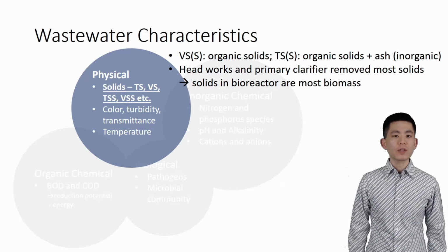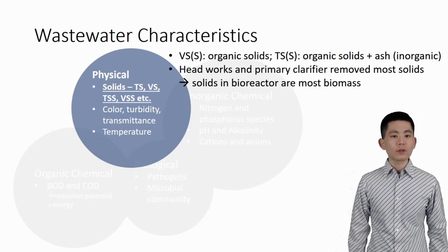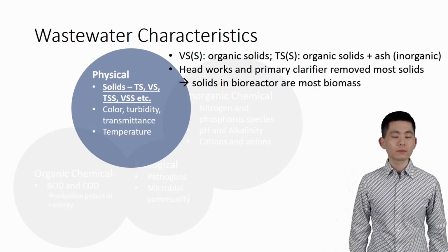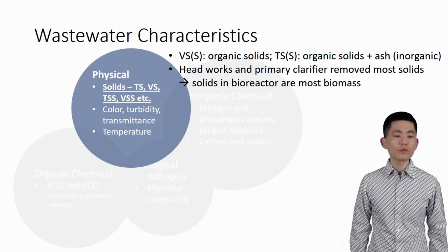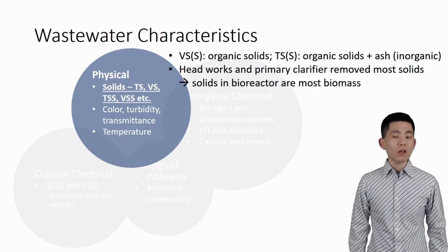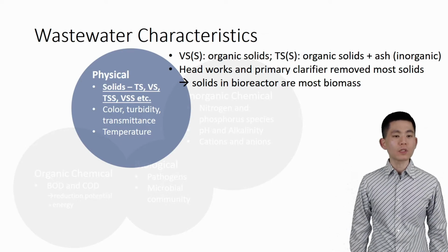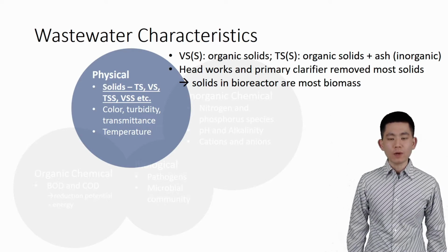The suspended solids are determined the same way, but with the solids collected on the filter after filtering a certain amount of sample. Because the headwork and primary clarifier removed most of the solids before biological treatment processes, the solids in biological processes are mostly the biomass grown using the soluble organic matter as substrates.